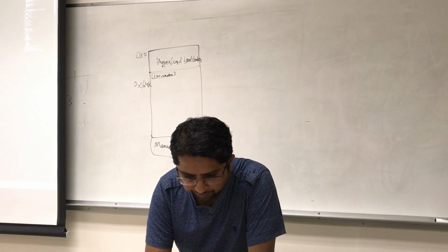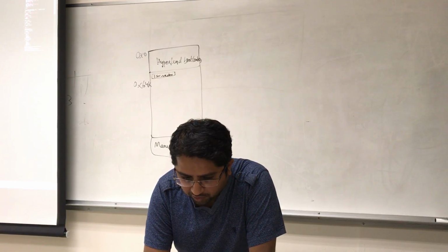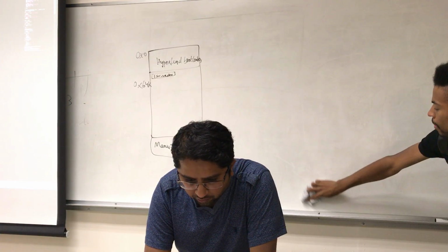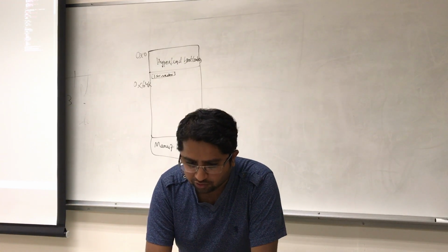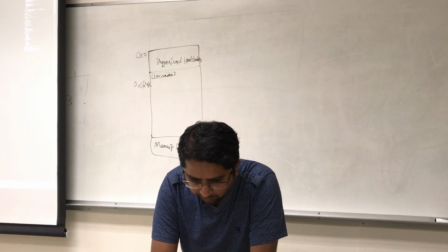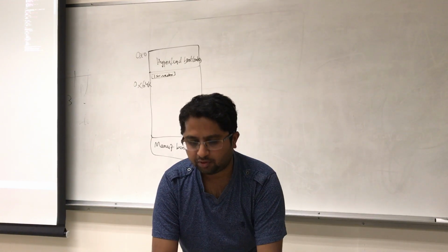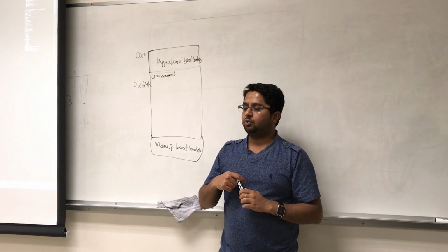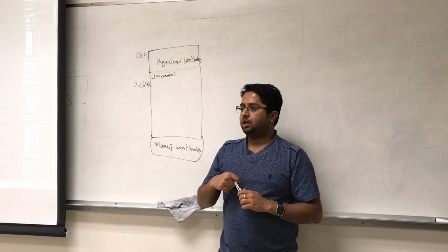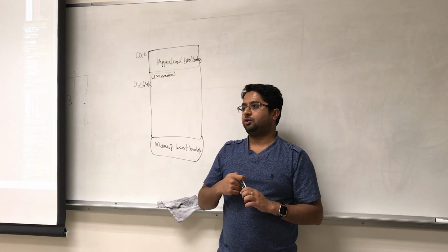Right, so let's go back to startup.cpp. Now the array that you look at, starting from 150, is all your software or the user interrupts. This is where you can actually set up what kind of interrupt you want, and this is one of the ways to actually address your interrupt.